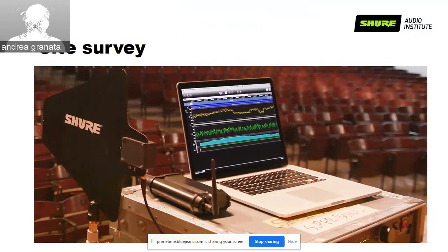What we are looking for during a site survey is, number one, is there any TV channel or any permanent source of interference in the spectrum that we are planning to use? Second question, are there other users in the environment that we are going to use? So who else is using RF systems?